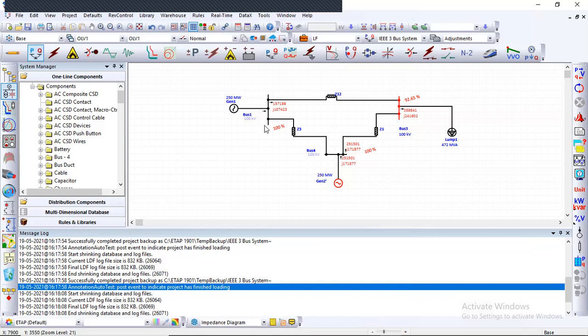Okay, these are the things which I need to explain to you guys: generator 1 produces electricity and provides it to bus 1, which also shares the load via impedance Z12 to the lump load. Similarly, the generator produces electricity, with a rating of 250 megawatt, providing it to this bus, and this bus is also synchronized with this generator. This bus also serves the load of lump load 1 by impedance Z1.